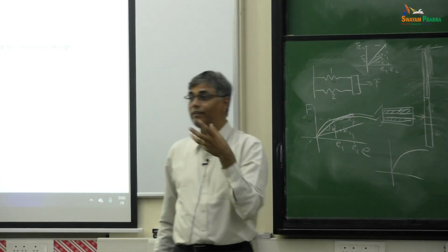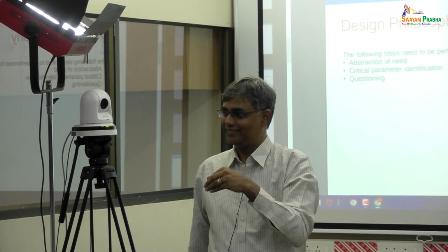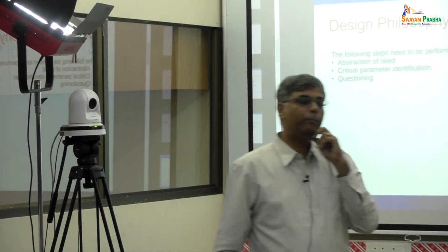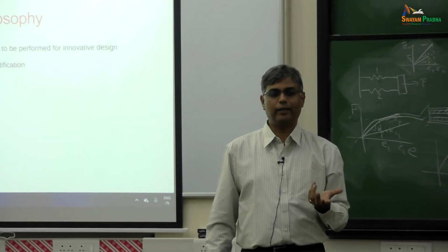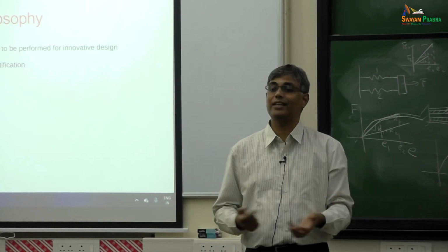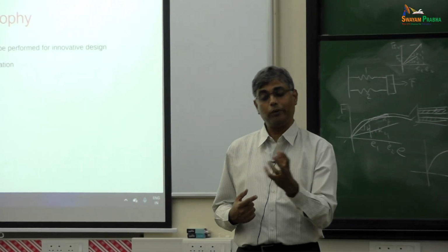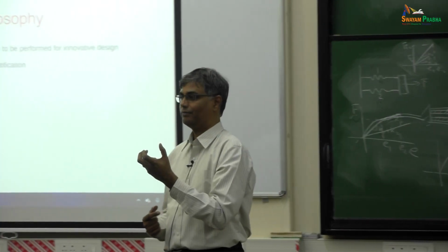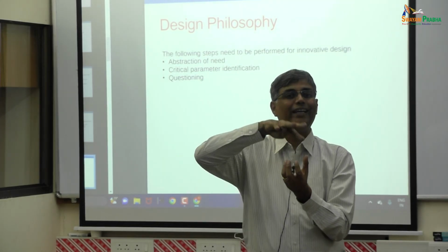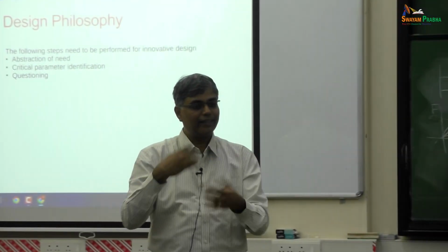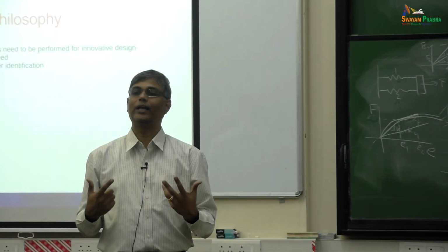But he's asking, can I do it even more in some other way in which I can literally get those detailed properties? To be perfectly honest, there are some techniques that are being developed. Those are called non-destructive testing. For example, there's something called CT scanning technique, computed tomography. CT means an X-ray. So people do an X-ray of objects and find out how the density is varying from point to point. Using that, they try to see if they can back calculate. It's okay, it doesn't work that well, it's very complicated. Sometimes you wonder whether it's worth the time.